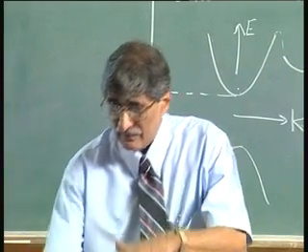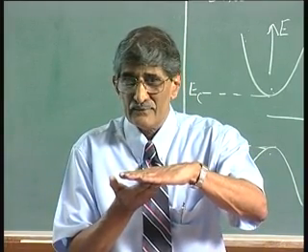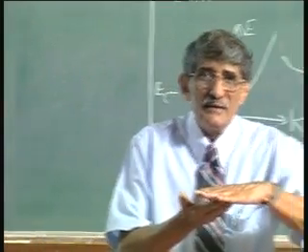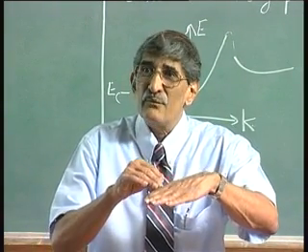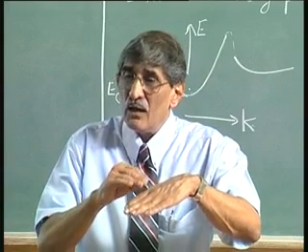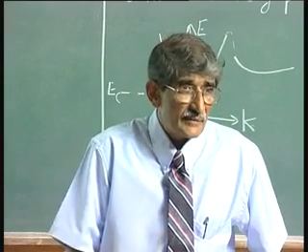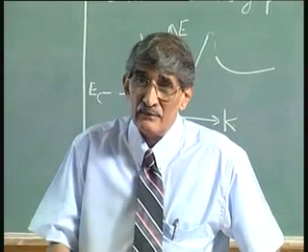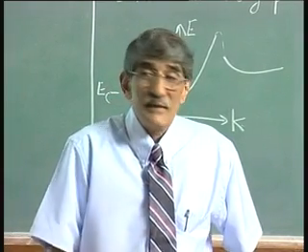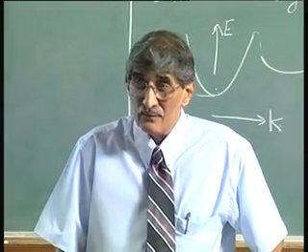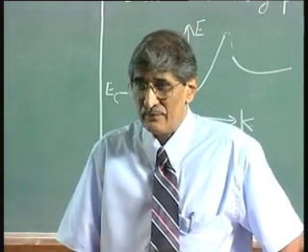If the junction is somewhere on the top, and on the other side you have the contact with the ambient, now the heat generated at the junction should flow to the ambient. That flow is by conduction. How much flow is there by conduction depends upon thermal conductivity. The higher the thermal conductivity, the better. That is where silicon is scoring over other materials. You will see silicon carbide, if you examine, has even better thermal conductivity than silicon. So, that is why people look to silicon carbide for power devices, not for high speed devices.